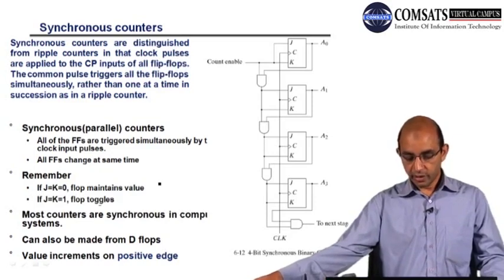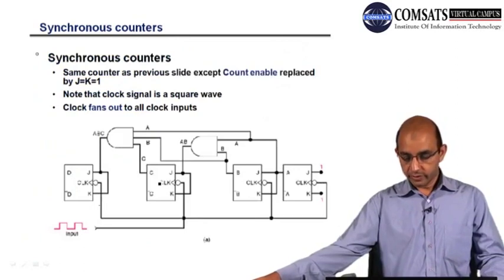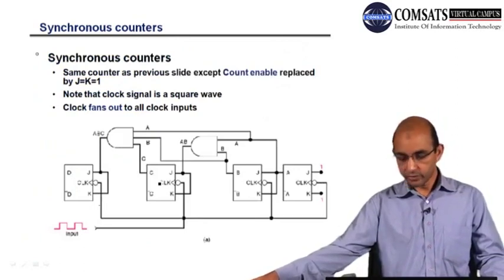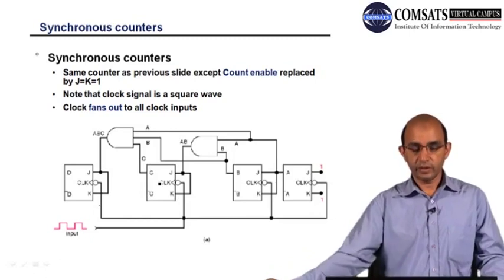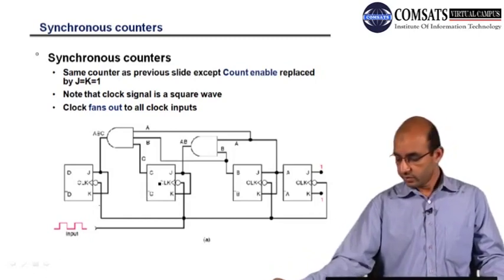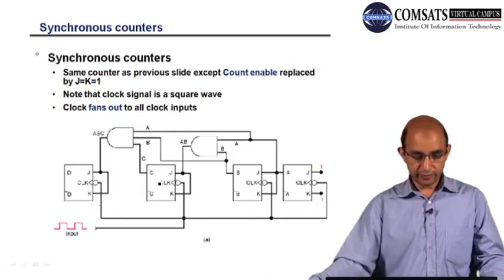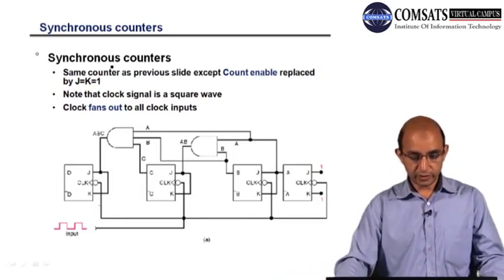Usually in computers we use synchronous counters. We can also make those counters using flip-flops, and we will see them after a couple of slides. So here we have the synchronous counter. You can see the same clock pulse for all the flip-flops, indicating the synchronous operation.